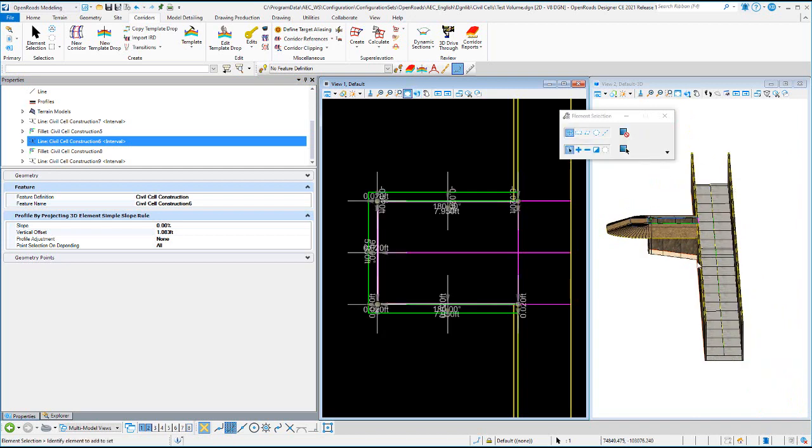You see this thing is sloping up, and it's because of that vertical offset. In other words, I think I did a slope projection off that bottom of 0%, but I raised it 1.083, and so you could change that value to change that slope or that offset that you're seeing out here.